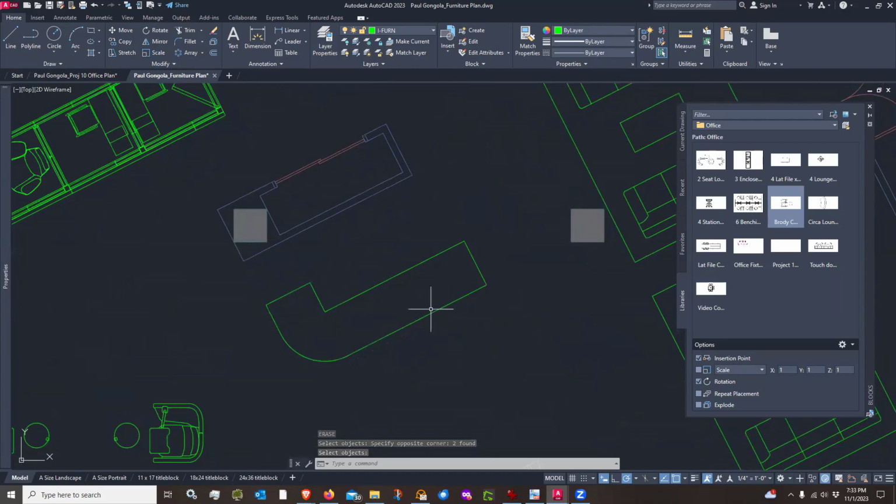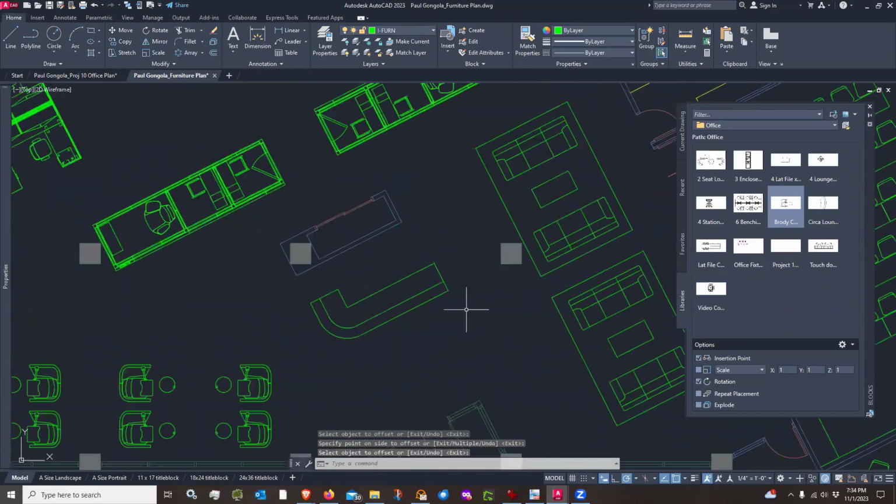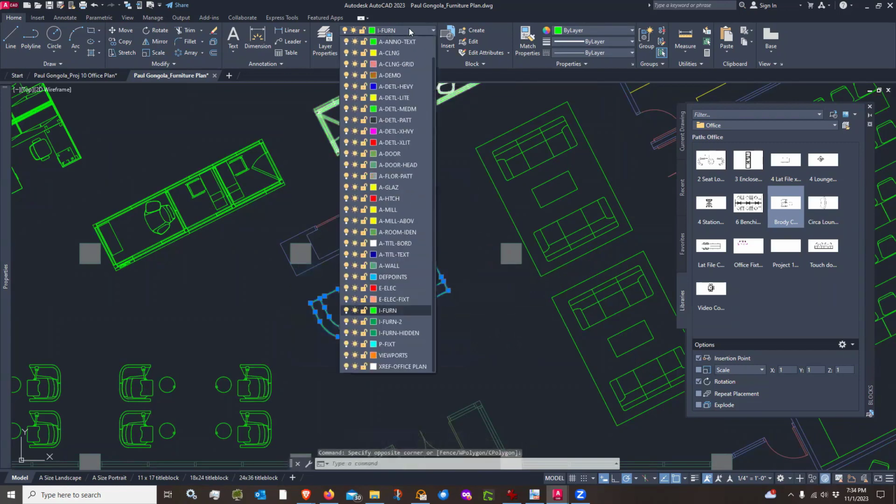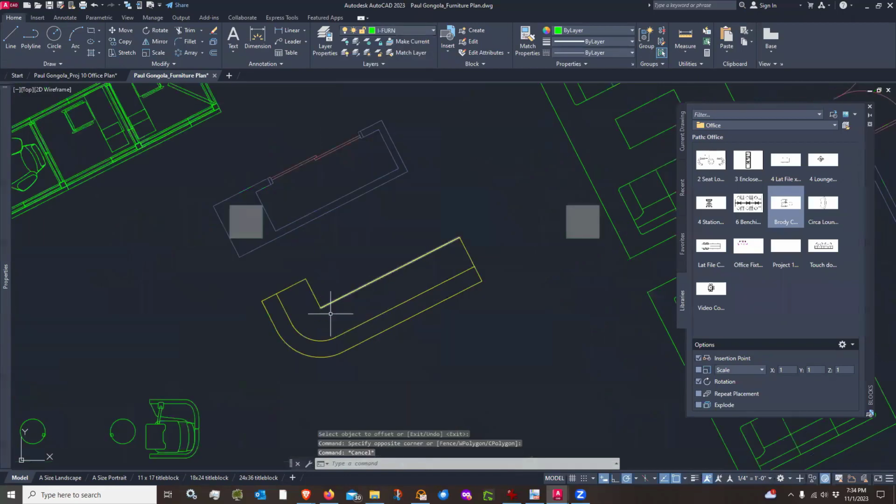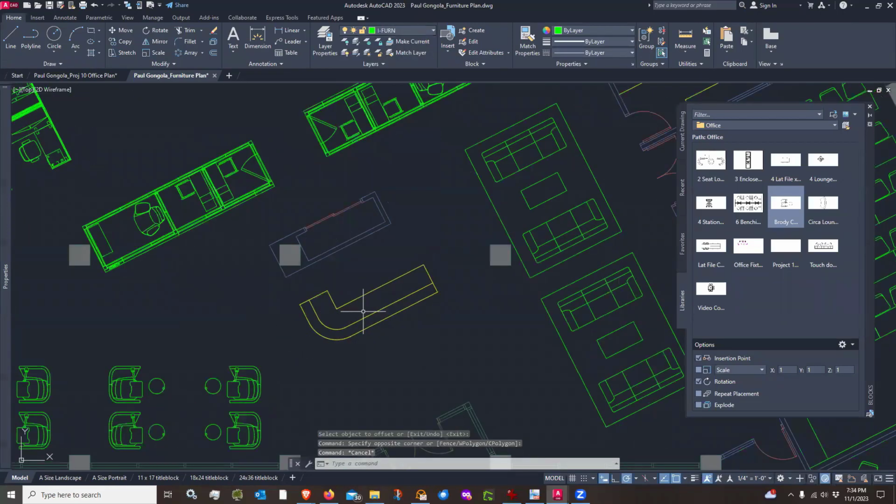And then I've got a transaction top. That transaction top's 12 inches. So I'm just going to use offset. 12 inches. Offset this line. Offset the curve. Offset this line. And I think I'm golden. The only thing that's wrong is it's on the wrong layer. So I'll put it on millwork because this is not furniture. This is millwork. And I want to give them a chair.